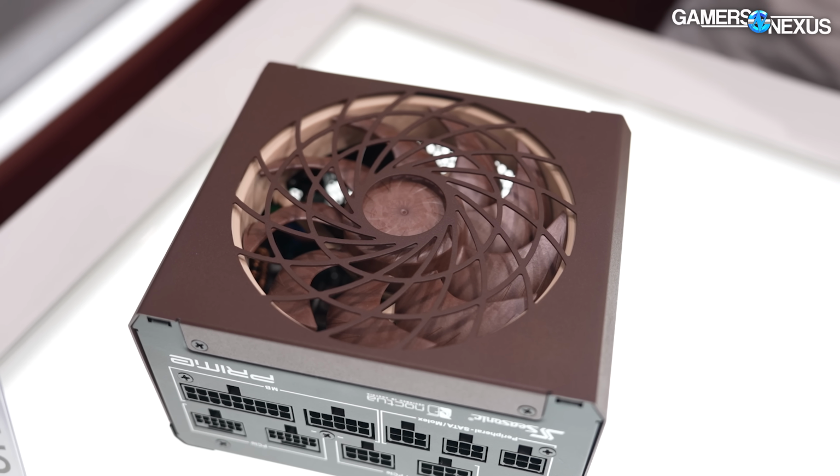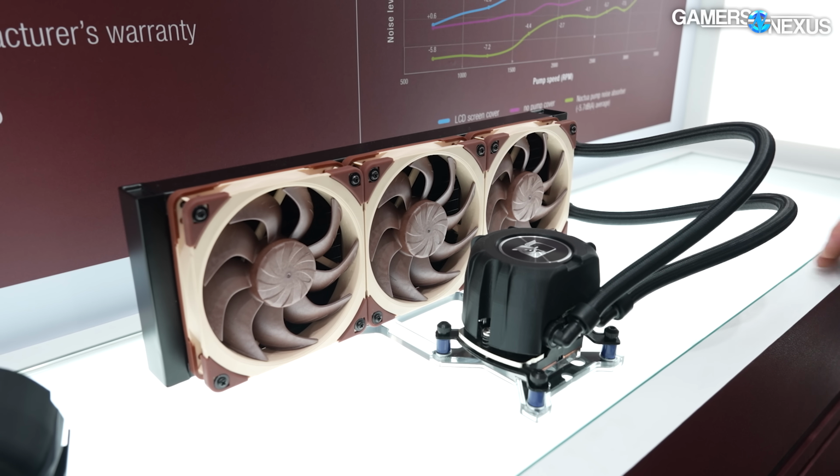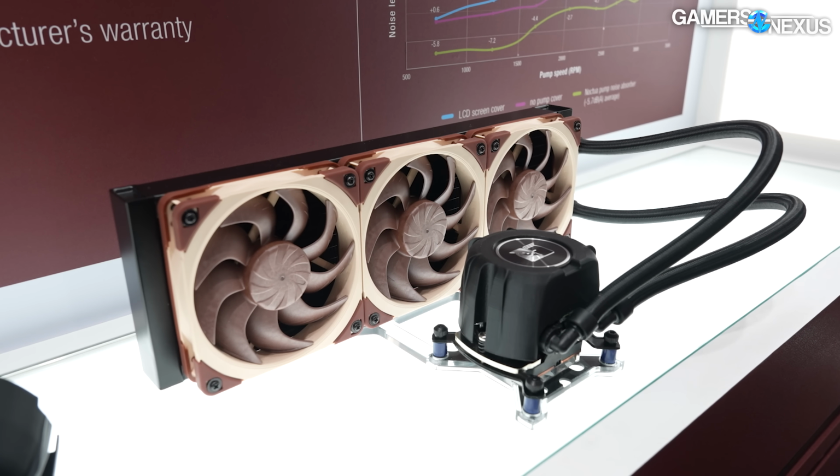Like of course, you could build a metal fan. But why would you want to build a metal fan if you want to let it run at like 20 to 25 dB? You would want to go metal or even harder engineering plastics if you want to go 6,000 RPM on a 120 millimeter fan, or 10,000 RPM on a 120 Delta Chopper. Then it could make sense, because then you are dealing with a level of vibrations, blade creep and drag forces that could all benefit from stronger materials. But for the market space we are targeting, I'm not really seeing it.